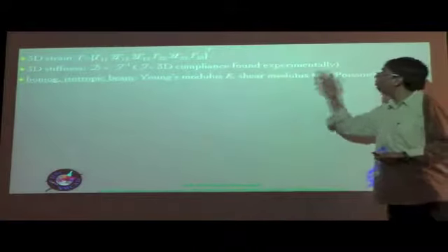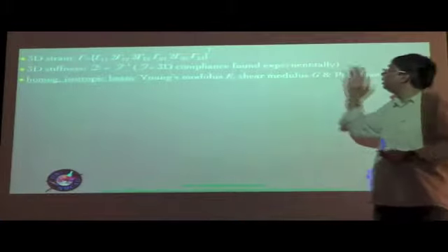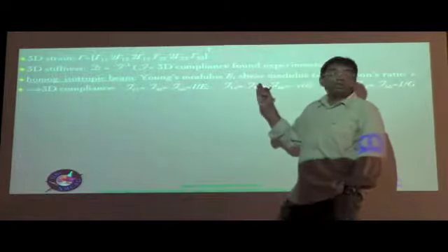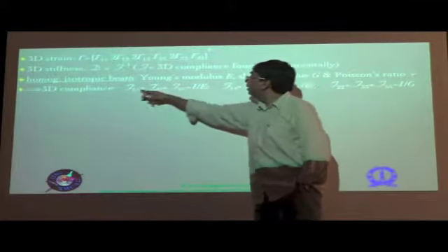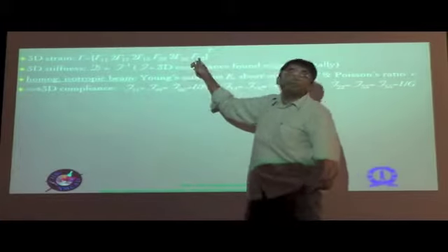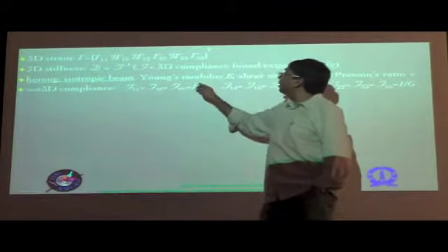It could be two of these three quantities, namely the Young's modulus E, shear modulus G, or Poisson's ratio nu. In terms of them, the flexibility matrix is quite easy to see. The diagonal terms, in the first, 4th and 6th positions, correspond to just 1 by E. That's how you determine the Young's modulus of a material.